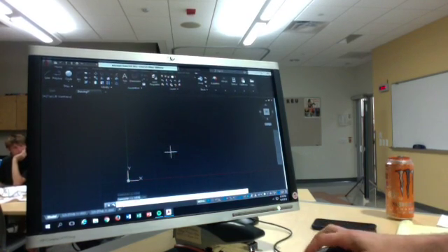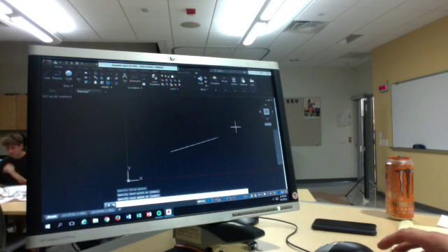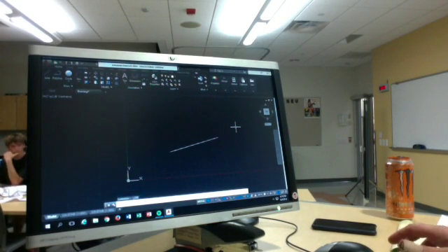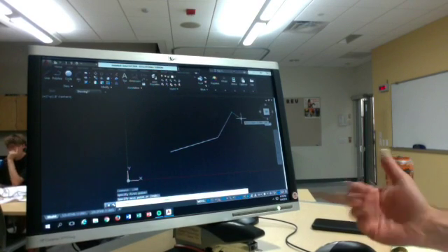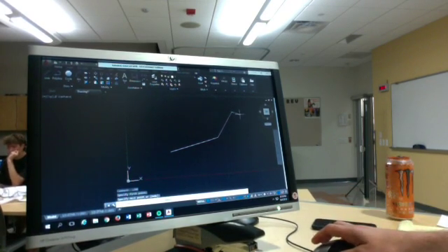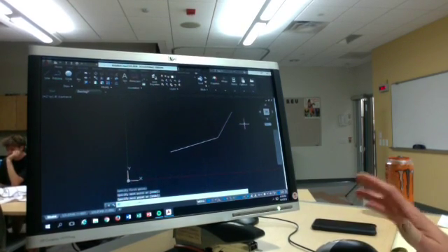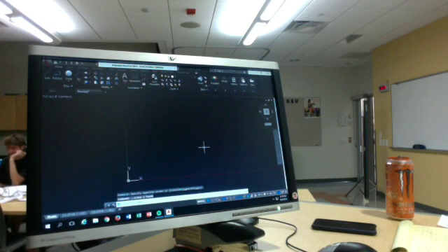Or let's say you're in the line command, and you draw a line, and you're all done. You hit the space bar. Or enter. Same thing. That'll get you out of the command too. Or let's say your keyboard stops working for some strange reason. You can right click and hit enter. So there are so many different ways to do the exact same thing in AutoCAD. It's kind of funny because this program is overkill and yet archaic all at the exact same time.